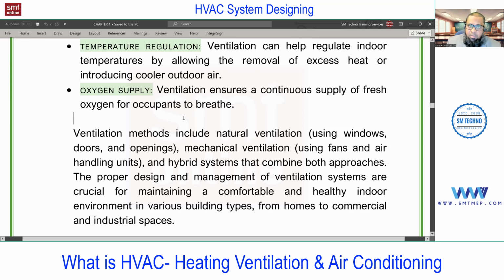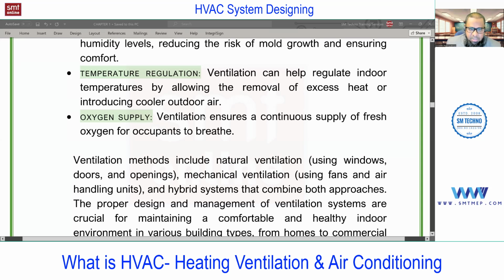Economizer means if the outside temperature is less than inside, in that case we increase the exchange of fresh air, and that is done with automatic motorized dampers. With that we can save energy as well as maintain the quality with less energy. I think you got the idea about the economizer, but don't worry, the economizer is not explained yet, I have just given the reference at this level. Just remember, if the outside temperature is less compared to inside, generally in the evening time, in that case we can provide more outside air, so that we get the advantage of saving energy while maintaining the temperature.